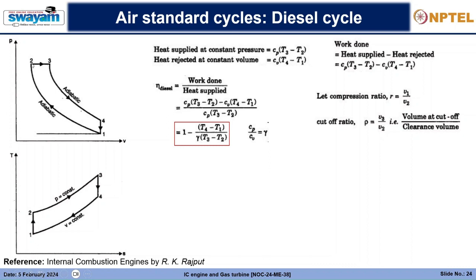From 1 to 2, the volume inside the cylinder was decreasing as the piston was compressing the air, right? So from 1 to 2 the volume was decreasing and the air is getting compressed, so the pressure increases at point 2.